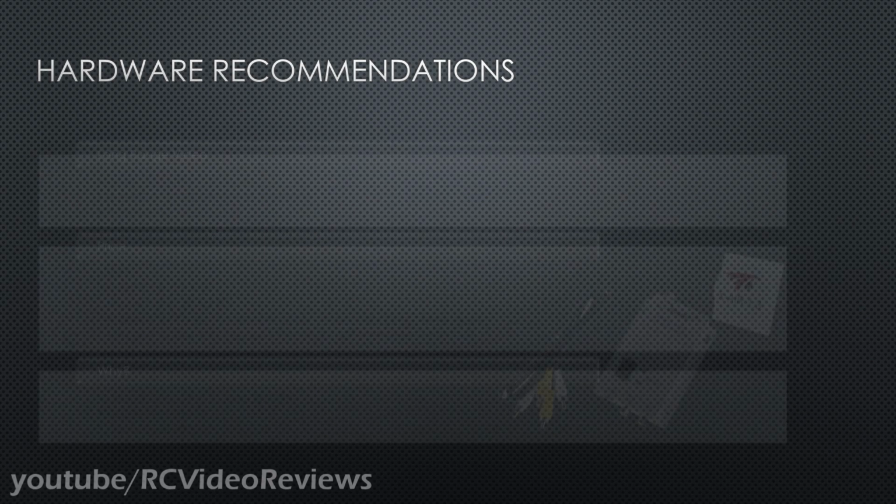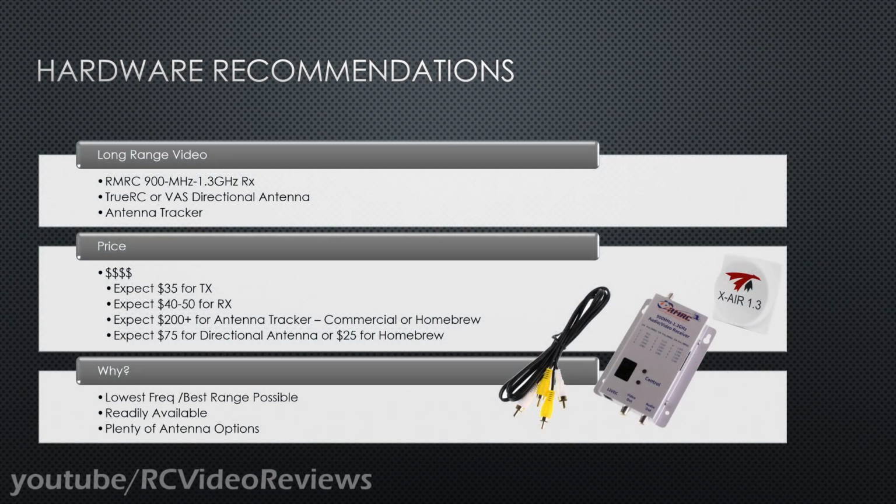Next up is long-range video. If you make the choice to fly long-range video, one of your best options is the ready-made RC 900 MHz to 1.3 GHz receiver. I like TrueRC or VAS directional antennas, and if you really want to maximize your range, you're going to need an antenna tracker.